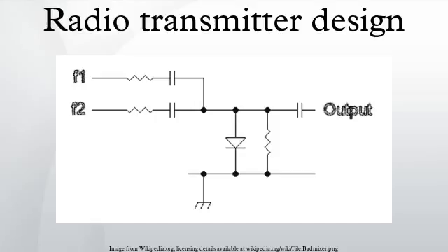More elaborate transmitters allow better control over the modulation of the emitted signal and improve the stability of the transmitted frequency. For example, the master oscillator power amplifier configuration inserts an amplifier stage between the oscillator and the antenna. This prevents changes in the loading presented by the antenna from altering the frequency of the oscillator.